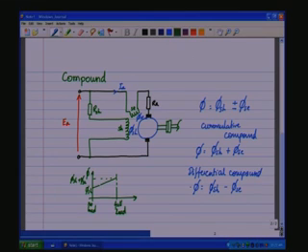the field starts from phi shunt value and starts decreasing. So, as the flux decreases, the speed will increase to maintain the back EMF constant. This means that in the differential compound there could arise some instability due to increasing speed, and that could cause some runaway issues. So, normally the compound motor is not wound for differential purpose. It is normally wound as a cumulative compound motor.